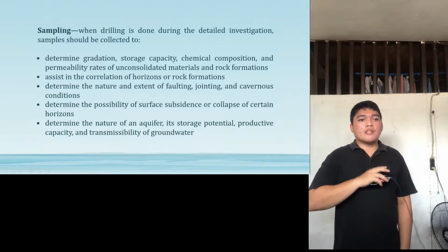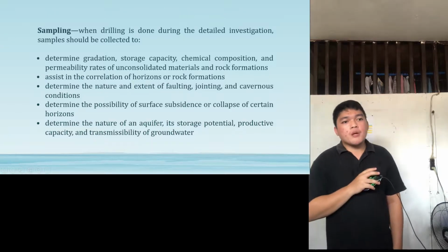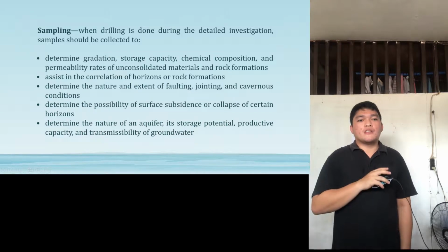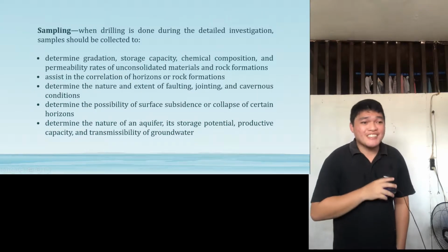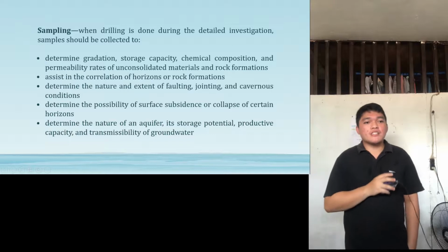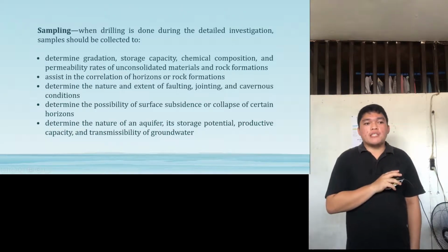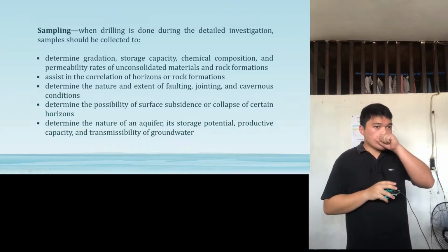Determine the nature and extent of faulting, jointing, and cavernous conditions. Determine the possibility of surface subsidence or collapse of certain horizons. Determine the nature of an aquifer, its storage potential, productive capacity, and the transmissibility of groundwater.